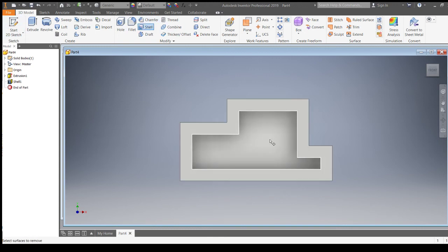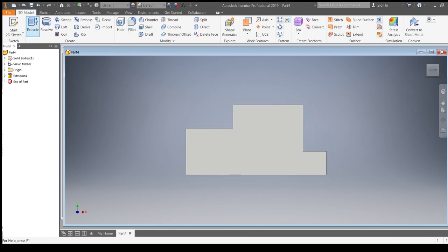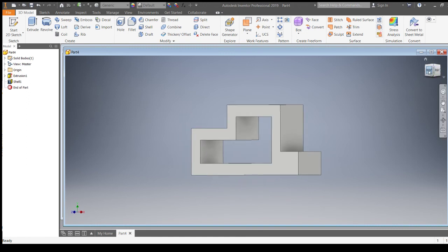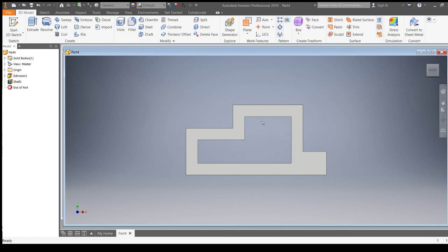And you can use the shell to hollow things out, like if I want to just cut straight through. I'm sorry, it'll do that sometimes. If I want to just cut straight through, I can do that. So I just have a hole in my object. You can cut through the sides. Just be careful. Sometimes they'll be a little finicky in the order in which you shell, but it will work for most cases. And changing the thickness of the shell obviously will drastically change the results.